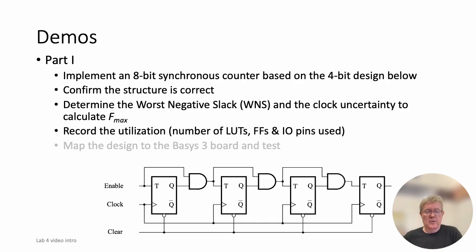Right, so the first part of the lab asks you to implement an 8-bit synchronous counter based on the 4-bit design that you see at the bottom of this page. You're going to be implementing a structural counter, having designed a toggle flip-flop. That toggle flip-flop can be described behaviorally, but once you've described it, you need to instantiate it 8 times with the AND chain as you see in the diagram below, so that it's a synchronous counter with an asynchronous reset.